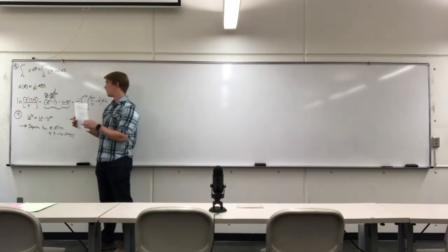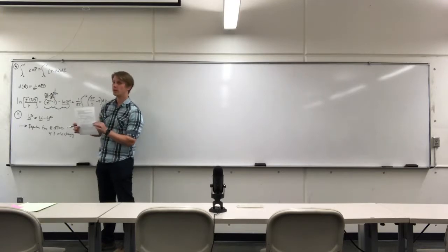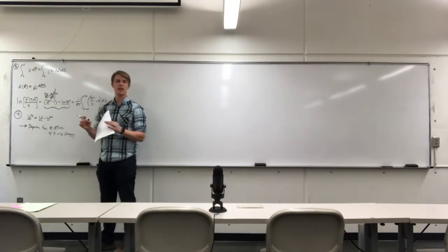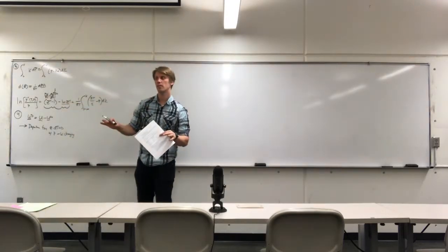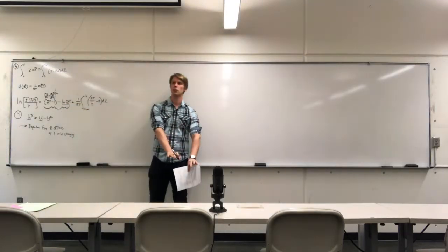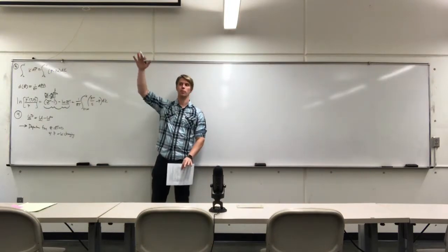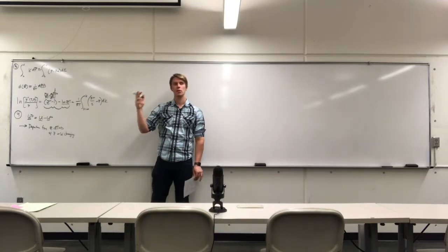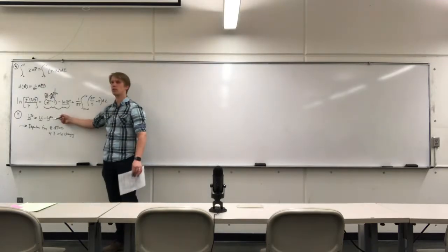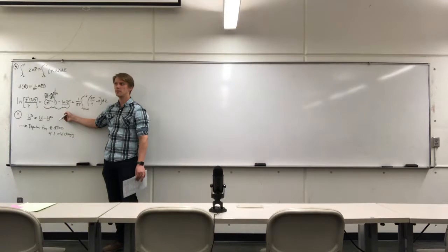So what's going to happen on homework 3 is we're going to be combining these together and basically developing an entire phase diagram, all the way from some arbitrarily low temperature to the critical point. In addition to the phase diagram, getting the vapor pressure, the saturation temperature, saturation pressure, volume of the liquid, and volume of the vapor, we're also going to be calculating the internal energy, the enthalpy, and the entropy.